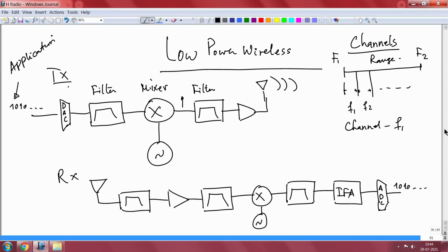So essentially all of that means you have to design this filter properly so that there is no leak of energy from f1 to f2 and so on, right. They are very closely spaced, okay. So there are terms like adjacent channel interference and so on, which you can avoid by designing very sharp filters so that no energy leaks from one channel to another channel. That is all about analog design, we do not need to worry about it.